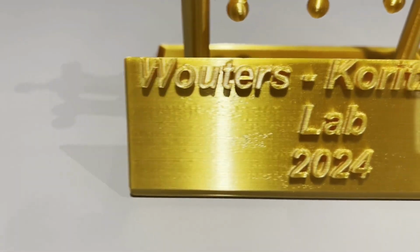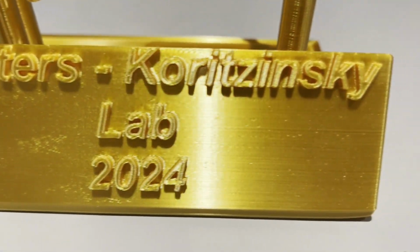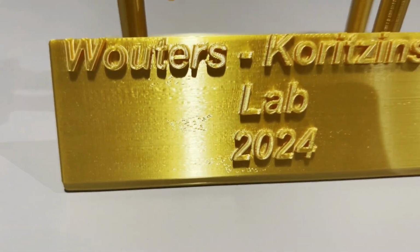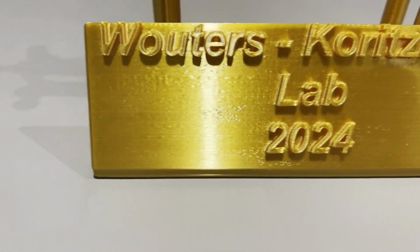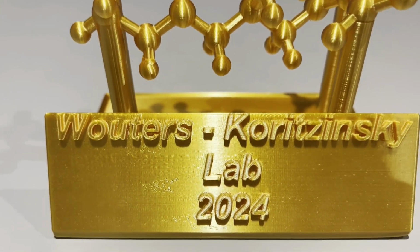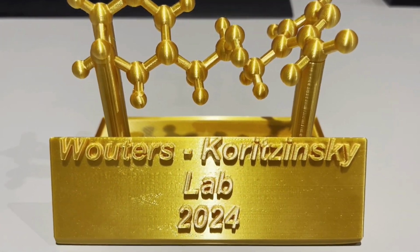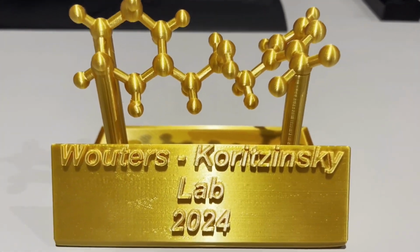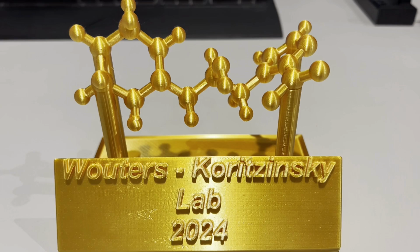But overall, I do recommend the Arial font. Don't remember if this was italicized or not, but it did a fairly good job. Now, of course, this isn't a top-of-the-line printer, so you are going to have some printing artifacts. This blobbing, discontinuity, whatever you want to call it, was probably caused by too high of a print temperature, because this is printed at a 220 degrees Celsius nozzle, 60 degrees bed. However, I opted for a higher printing temperature than average because I wanted to ensure the layers were sufficiently adhered to one another.